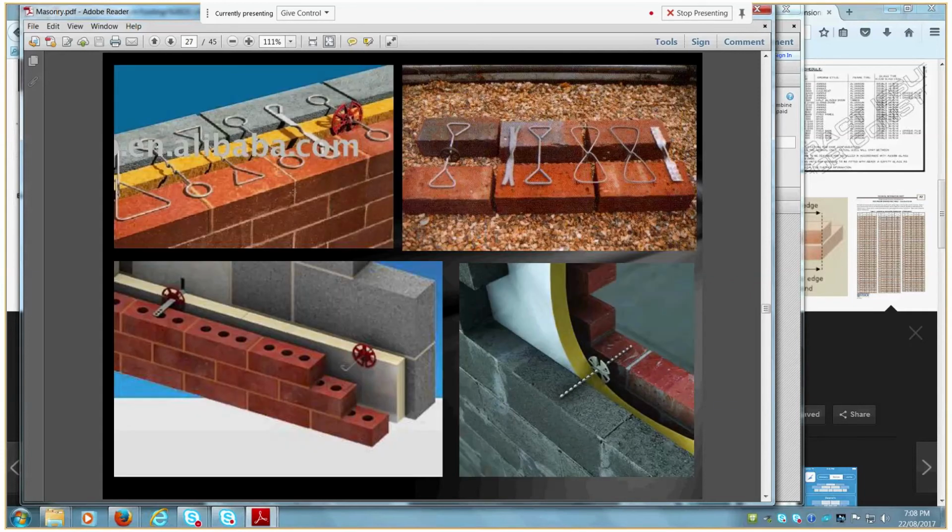And here's some example of brick ties. These brick ties with the small wheels on them are to hold the insulation in place, and that's holding the insulation to the internal wall. So that face of brickwork can have some moisture pass down without affecting the insulation, and also to help that insulation insulate this concrete block wall more effectively.